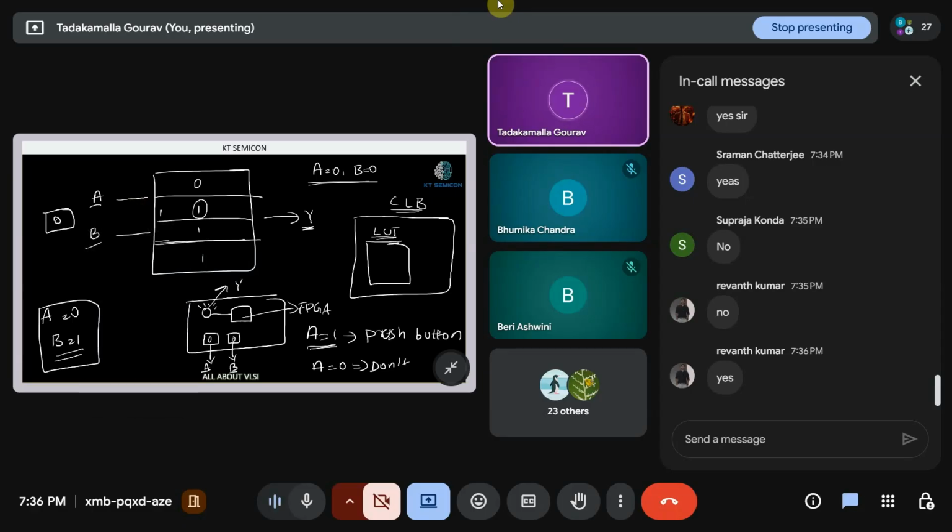Is it clear? It's simple. It's a simple static RAM, a simple memory where all the possible values of that particular gate are present. If we provide particular values, it works accordingly. It doesn't know what we are implementing, whether an AND gate or an OR gate. It has just stored a set of values, and according to the addresses we provide, it provides the set of values.